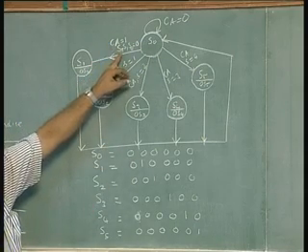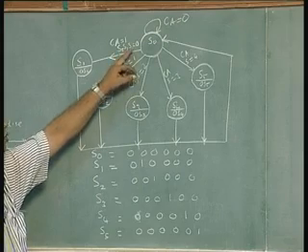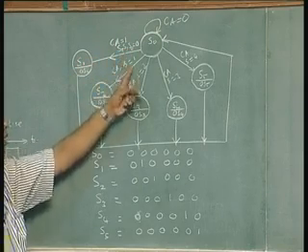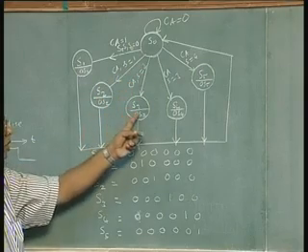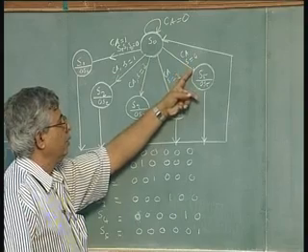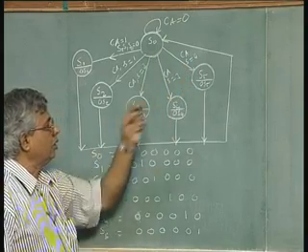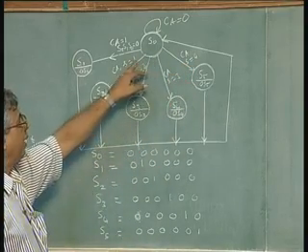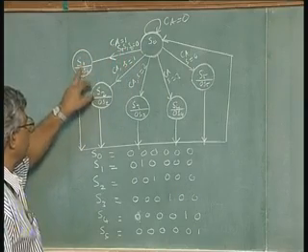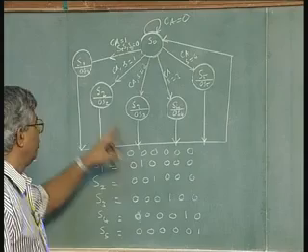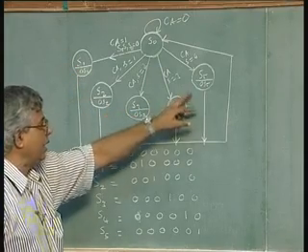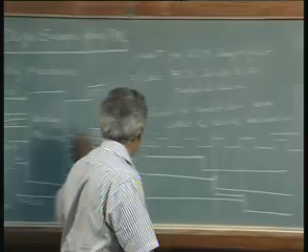CA is 1, and then depending on the selection made, as I said, S2, S1, S0 is 0, 0, 0, the first choice. It is 0, 0, 1, second choice, 0, 1, 0, third choice, 0, 1, 1 is the fourth choice, 1, 0, 0 is the fifth choice. So, based on the choice and CA being 1, it will go to the next state, the state being S1, S2, S3, S4, S5 for each of the combinations YS0, YS1, YS2, YS3, YS4. That is the reason we call these signals YS1, YS2, YS3, YS4, YS5.